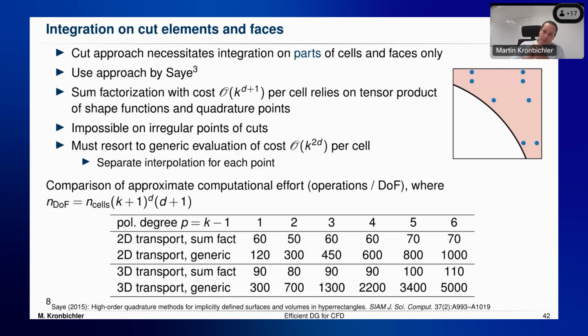The other thing is, instead of using simplex elements for higher degrees, you could also use this embedded tensor product. So essentially having this Nektar++ approach. What they are doing is essentially having collapsed tensor products and expanding it during the evaluation, where I also think that you would probably lose a similar factor, maybe 3 to 5 as well, on intermediate degrees, like say degrees 4, 5, 6 or something like that. I don't know what your experience is, but my experience is that they're slower, but not to such a big extent that you would not use those meshes at all.